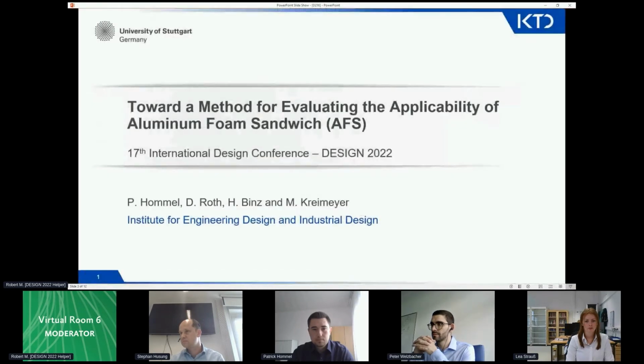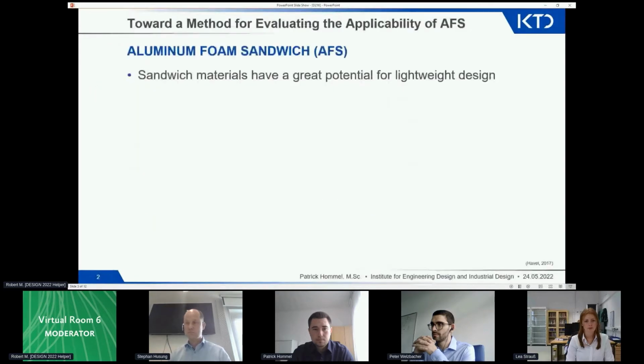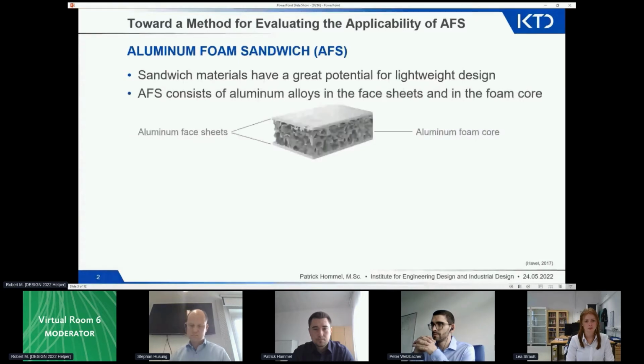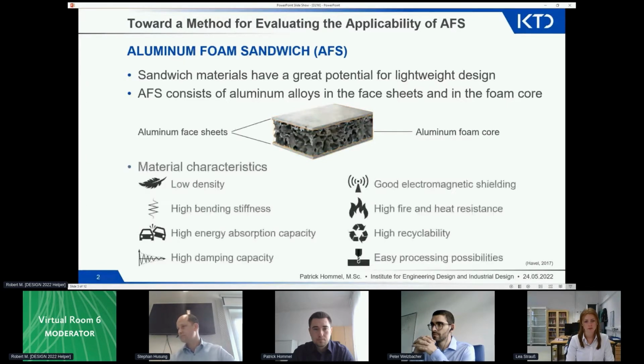Hello everyone, my name is Patrick Hommel and I would like to present you our contribution about a method for evaluating the applicability of aluminum foam sandwich. Sandwich materials have a great potential for lightweight design, especially aluminum foam sandwich, which consists of aluminum alloys in the face sheets and also in the foam core. This material has many benefits, for example, a low density at a high bending stiffness and good energy absorption properties. It is also completely recyclable.